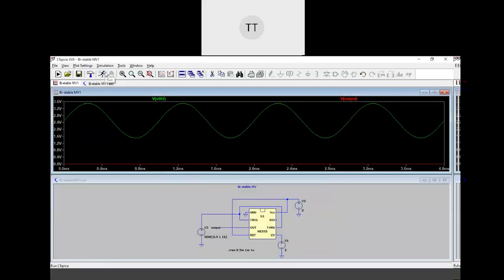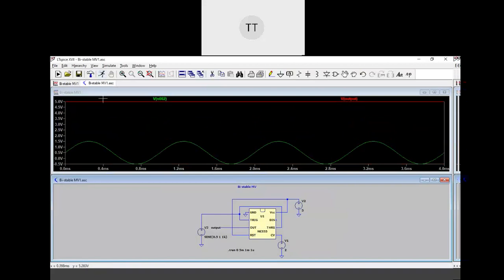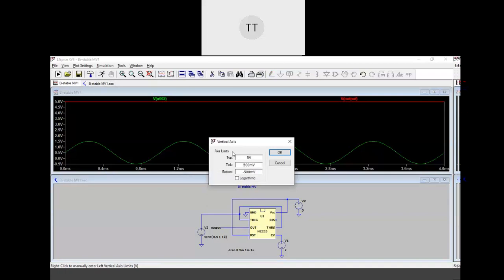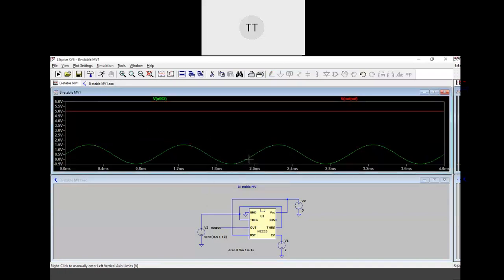You should see that. Is it there at VCC all the time? See that? Always VCC. Even though you applied the input waveform, since it is not crossing VTH, the output is not going down. So it is stable there. If it has to come to the other state, you have to exceed VTH. If it has to go back to the other state, it has to go below VTL. Done?